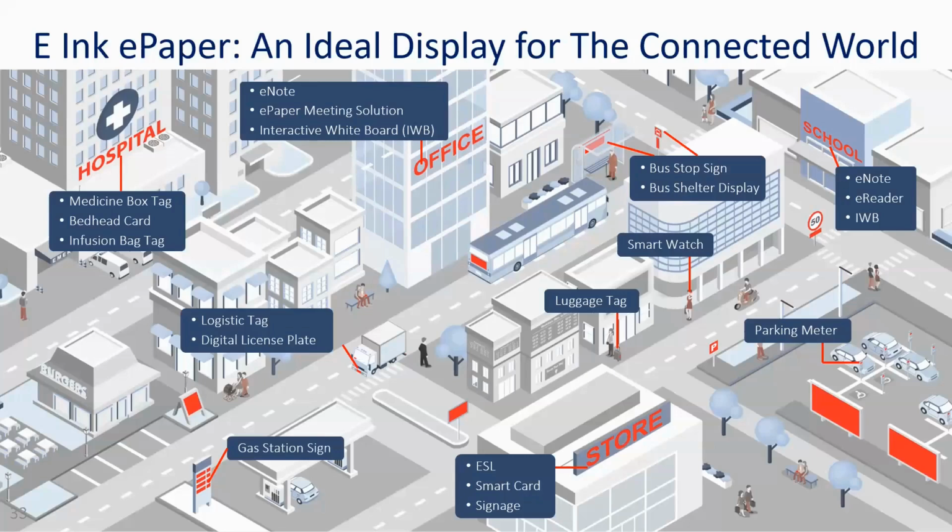Display technologies in general are taking typically about 25, 30 years to come to maturity. We've seen it at OLED as well. And e-ink is still growing. We now see it in more and more applications. And in this slide, you can see a number of the application areas where you can now find electrophoretic displays. And especially when you go into stores, the US a little bit less, I think, but in Europe, in Asia, and now also starting in the US, you will see that in stores, price tags are actually mostly using electrophoretic panels.